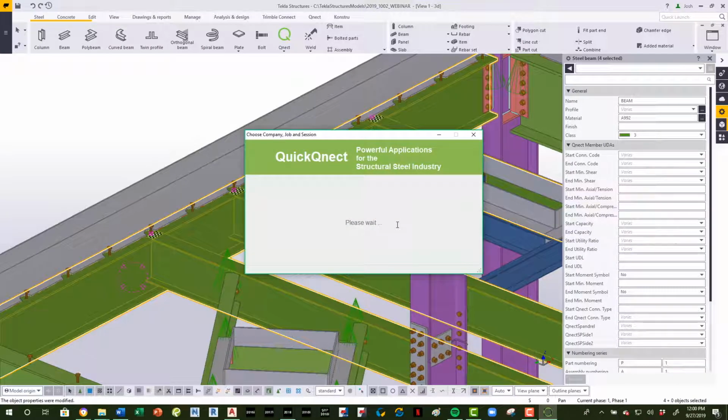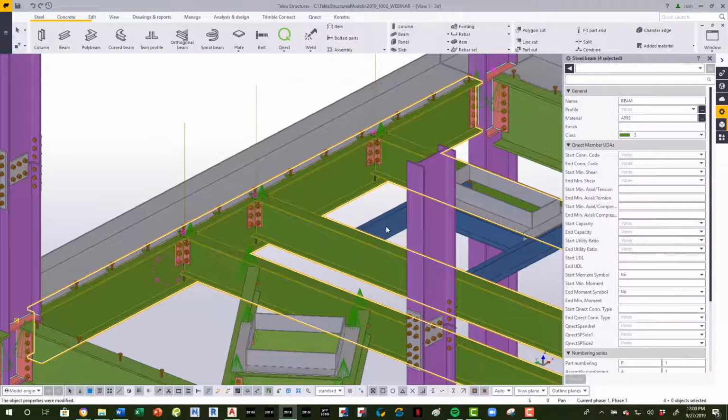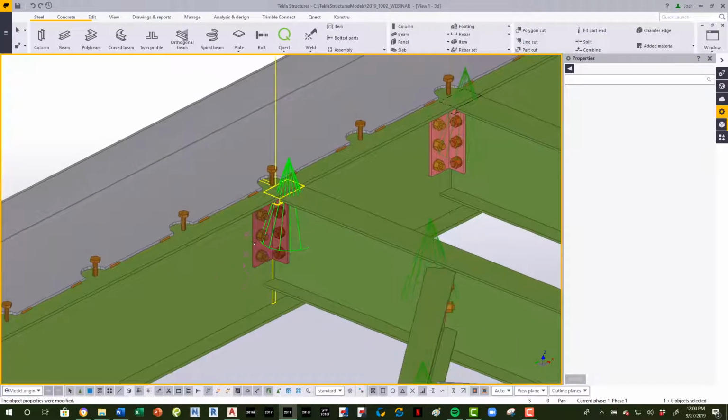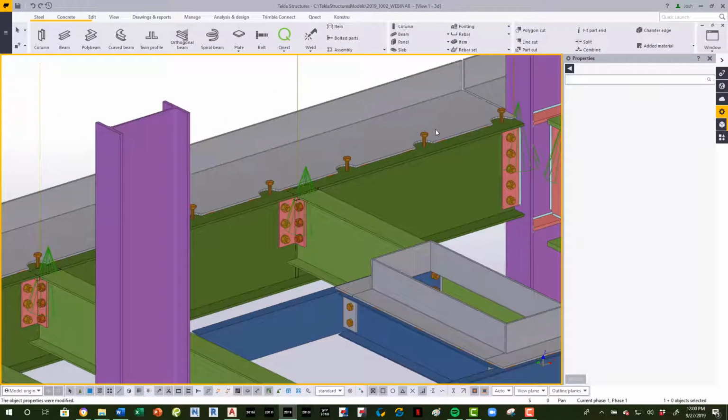The goal here is, if you're going to be able to do bolted in an entire location, or if you're going to be able to do welded in an entire location, you can maximize the efficiency. So you can see that these came in as bolted. Now, whether you have equipment or maybe you don't have equipment, all of your holes have been taken care of either manually or by your equipment. And now the only thing you have to do is physically come in and bolt these up, and you do not have any welding. All right, so now let's get into reducing time to fabricate.